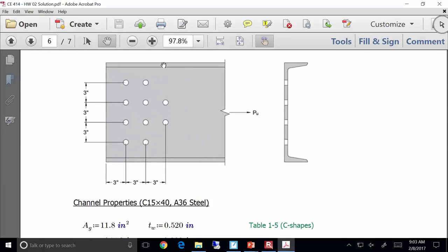so here's the channel. Remember, you've got to check all of the associated paths along the lead line. So for this, you've really got 3 potential paths. You've got path 1 that just directly cuts like that. You've got path 2 that can do this. Remember, it can be symmetric. You can flip it up and down. That's fine. And then path 3 will go like that, go down, and then go down like that. So you've got 3 potential failure paths. The third one was the one that ended up governing, but you've got to make sure you're checking all of them.